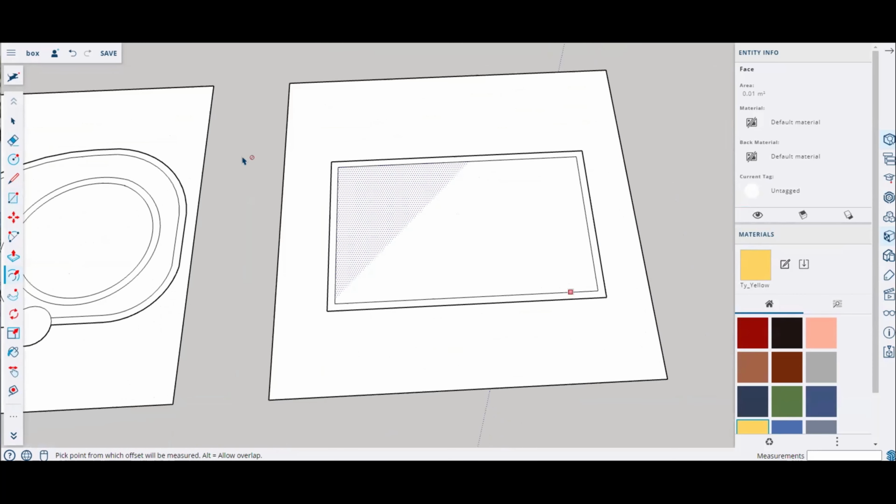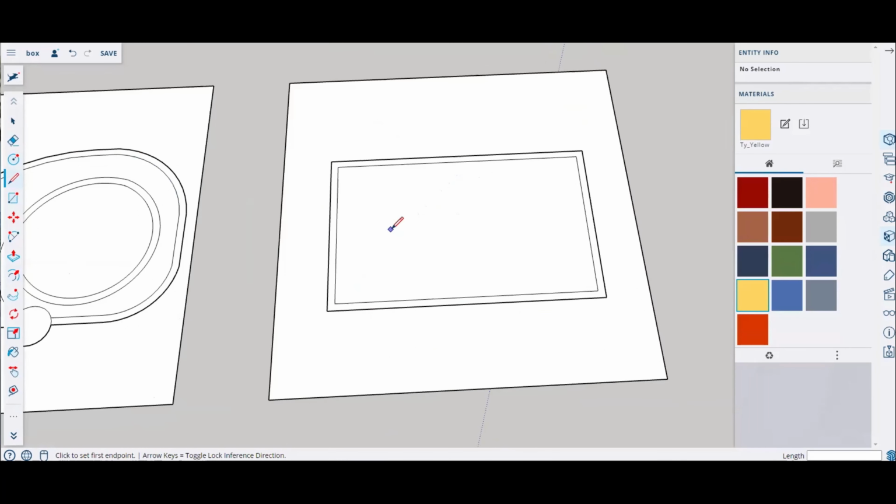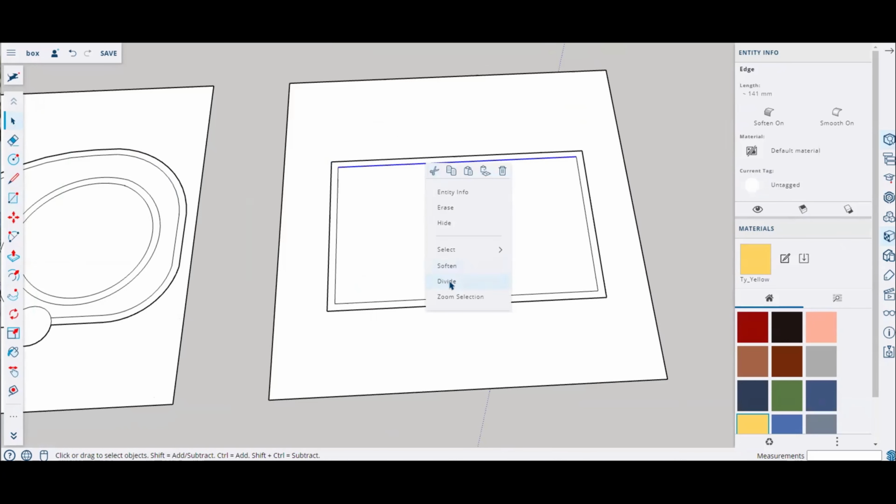All right. And let's say I wanted to do a T-line type of port. I can click onto that line, right click, and see where it says divide. You see it's got 3 red dots. If I start to pull on the left, it gives me all these different dots that I can use as reference, and on the bottom right hand corner it tells you how many segments there are. Looking at the scale of the thickness of the wall, we want the ports to be about, say, yay high, that yay thick. If I come along now, I can click into this and make these lines.